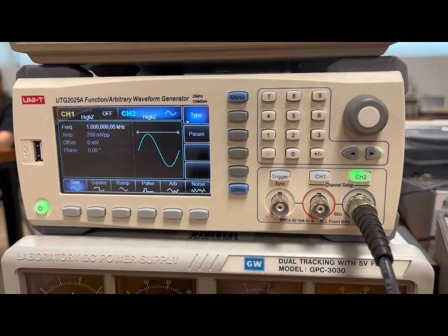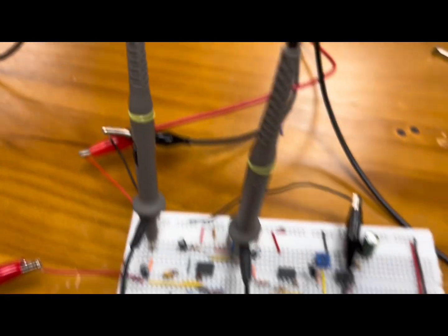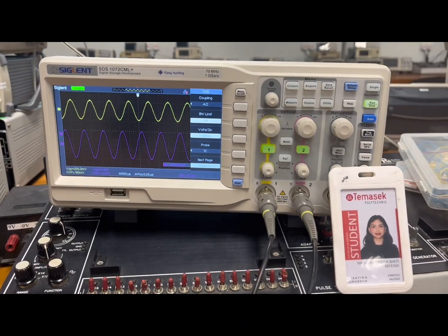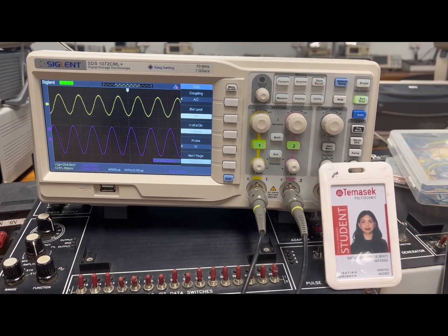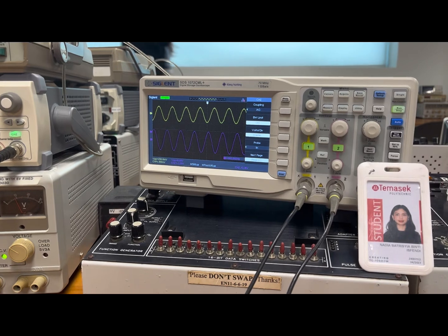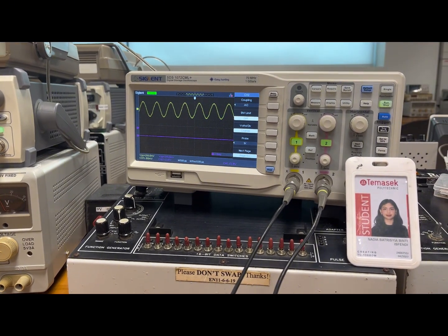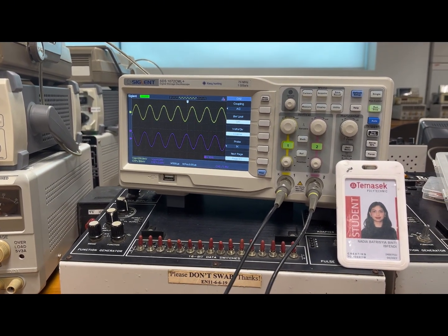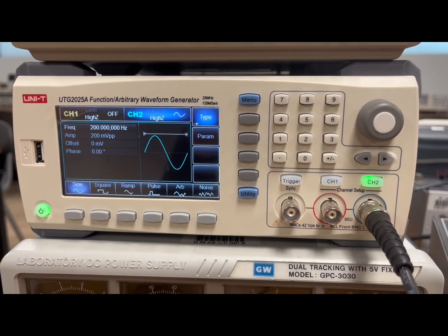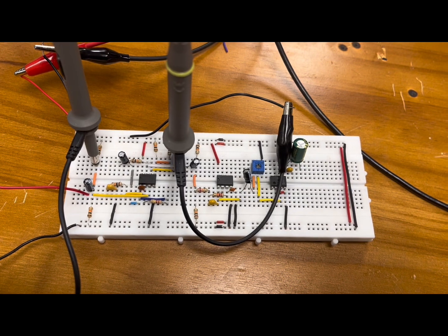At 1 kHz, we will put the probe at TP2 on channel 1, and all frequency as well as power supply settings are left untouched. We will then place channel 2's probe at TP3 and get an output voltage of 6 volts. By turning the trimmer, we can see how it affects the output waveform. As I adjust the trimmer, the waveform will be amplified and at some point become saturated or cut off. Set the frequency to 200 Hz without altering any other parameters.